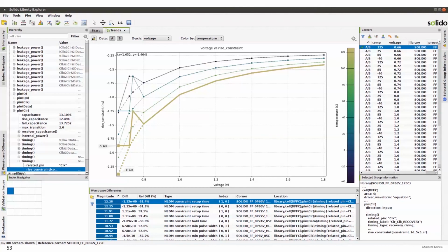Safety, yeah. So what we're doing in this space with SPICE and manufacturing variation analysis, specific to safety, is we're trying to show that there's enough margin. Let's say you really want to demonstrate that you've truly got a 1 in a million failure rate. Well, if you had to run millions of simulations to do that, you wouldn't be able to. But with our tools, you can demonstrate that 1 in a million failure rate with 1,000 simulations. And so you can show that you've got the margin that you're proclaiming, because you can now cover that whole space.